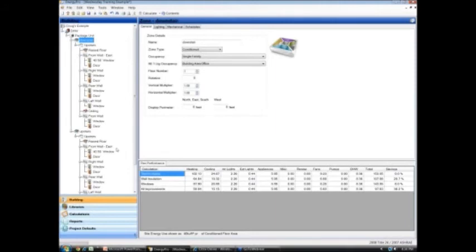If I replace my HVAC system and it's now more efficient, insulating my walls isn't going to save as much energy because I've got a more efficient HVAC system. So we have the individual results, and then we have the combined impact of those 3 things, or however many things you have.